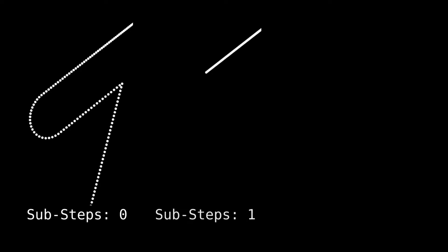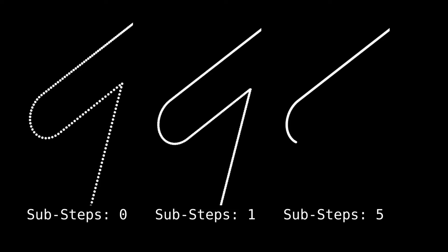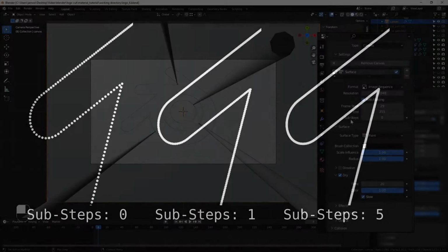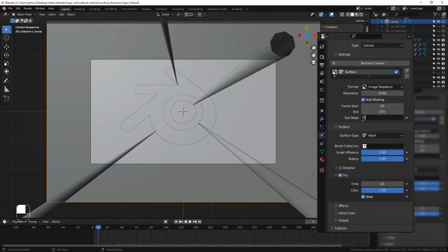What's going to happen is it's going to calculate the paint for every single frame of the animation. But because our cut tips are moving relatively fast, you're going to end up with big gaps in the paint. So this sub-step will calculate in between those frames, and I found that 5 sub-steps works pretty well for what we're doing.